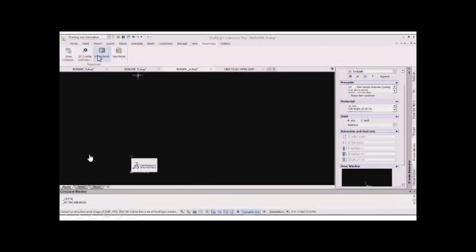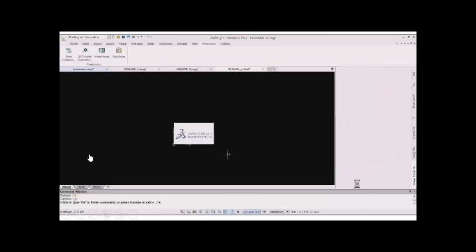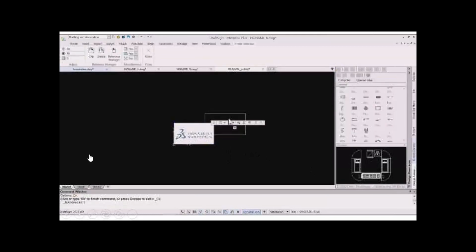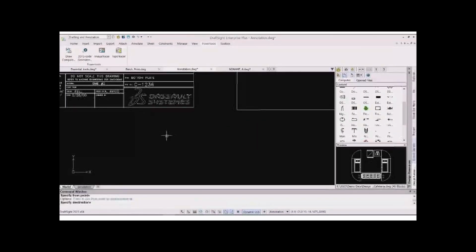So next one was Image Tracer. Image Tracer lets us convert raster images in .bmp, .png and .jpg format. These are converted to vector formats. The images can be architectural plans or floor plans or logos or curved images. The tool generates lines, arcs, polylines and curves from these vectorized images and places these objects into the active DraftSight layer. The Image Tracer provides preset profiles optimized for these types of images.